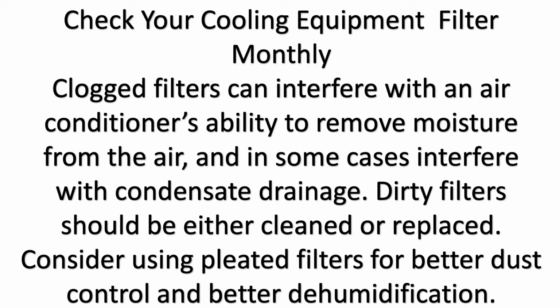Check your cooling equipment and filter monthly. Clogged filters can interfere with an air conditioner's ability to remove moisture from the air, and in some cases interfere with condensate drainage. Dirty filters should be either cleaned or replaced. Consider using pleated filters for better dust control and better dehumidification.